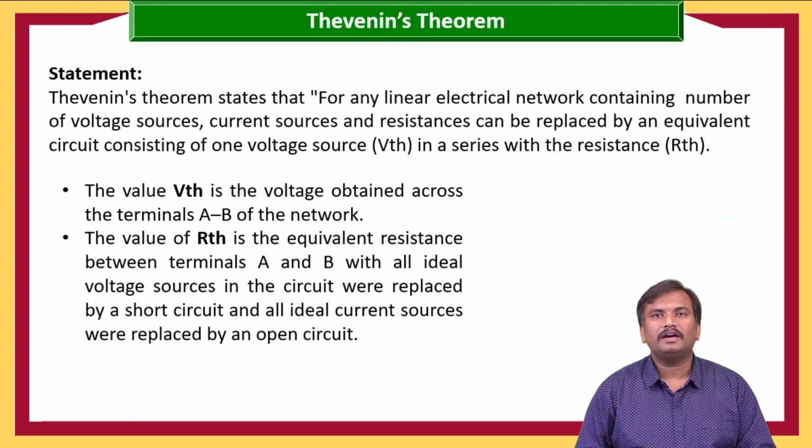Now first let us go with the Thevenin's theorem. The theorem which is given by Thevenin, that's why it is called Thevenin's theorem. Here the Thevenin's theorem states that any linear electrical network consisting of number of voltage sources, current sources and resistances can be replaced with a single voltage source in series with the resistance.